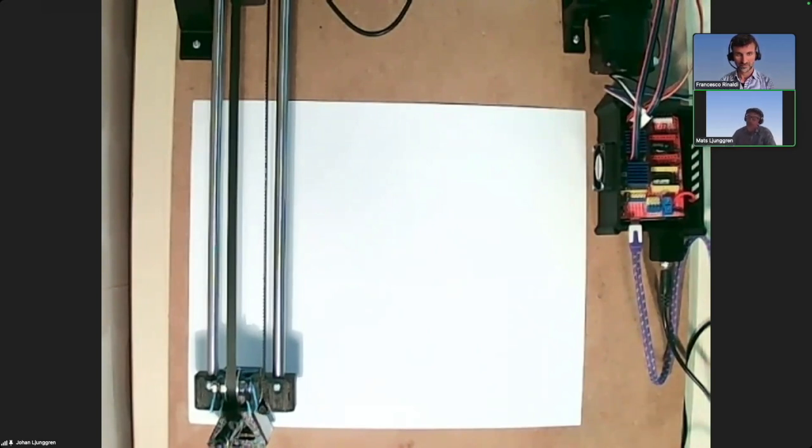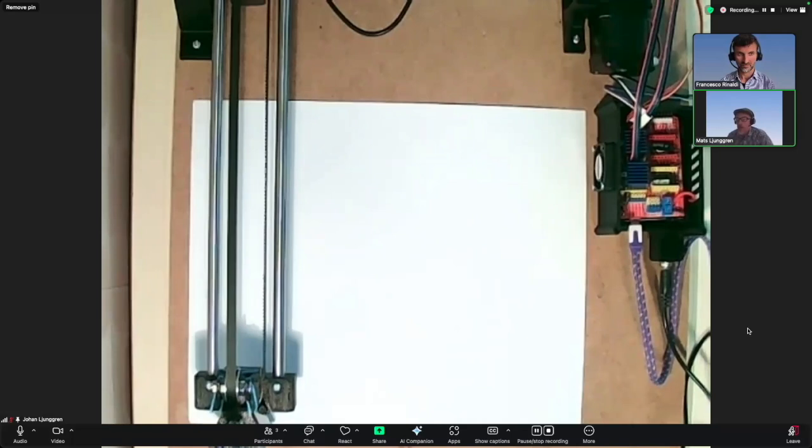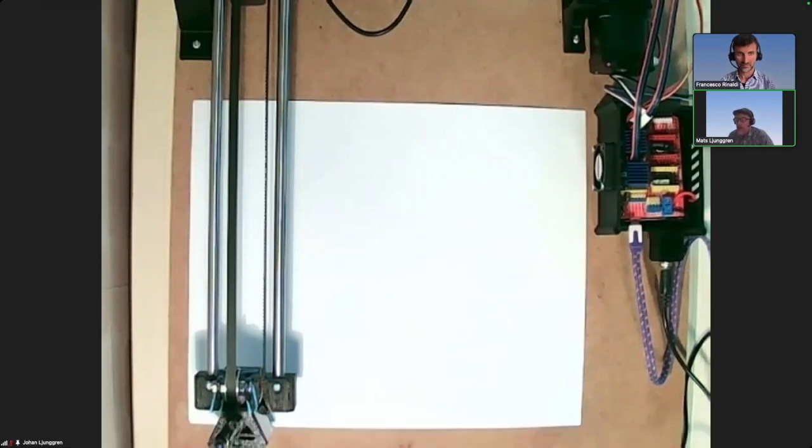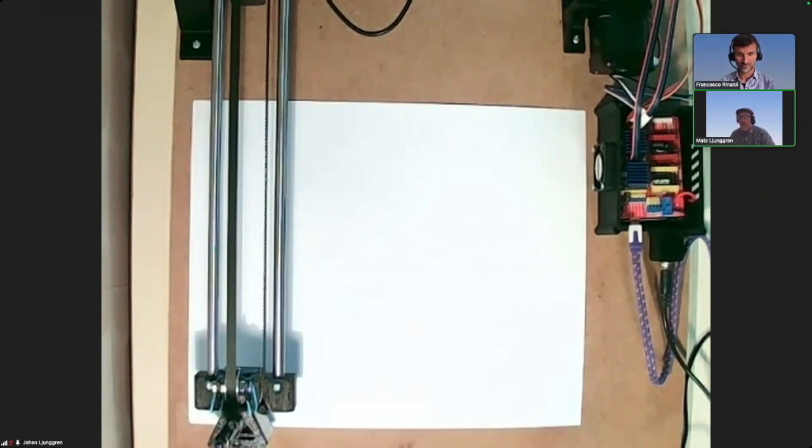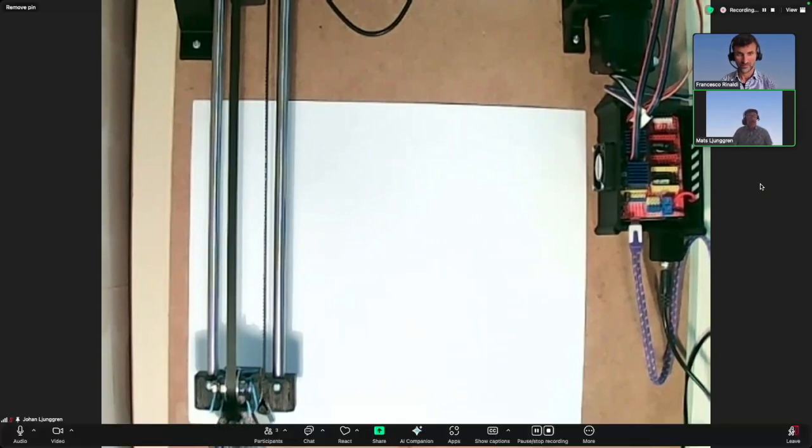Very cool. So to clarify, we are actually talking to the ESP32. It's running a piece of C code that opens up a WebSocket connection. So it's actually a server, and the software here is actually a WebSocket client, which is sending movement commands to the motion controller. So let me demonstrate how the code looks.